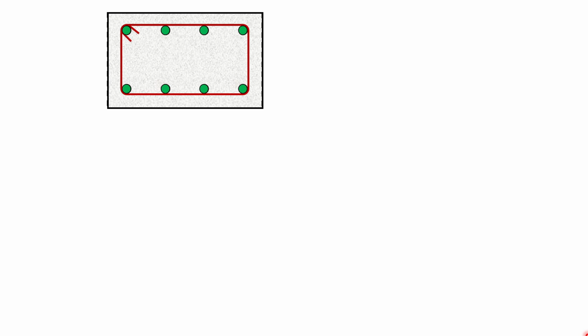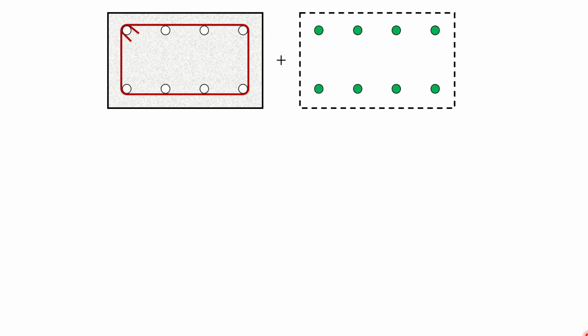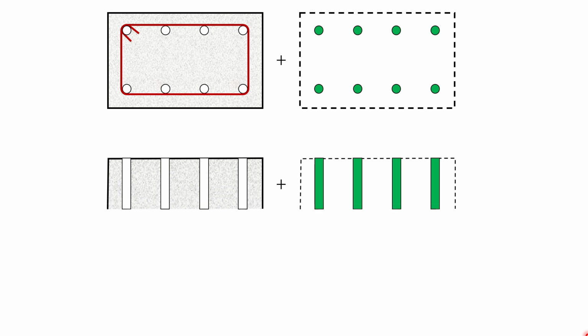Okay, next we try to imagine. We remove the rebars from our concrete column. Say for example, this is now our elevation for this plan view. We notice now that our concrete column here is being hollowed. Now because this concrete column is being compressed, of course the concrete reacts with C sub C force.